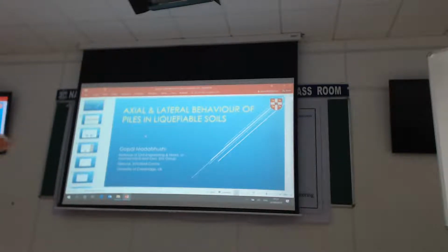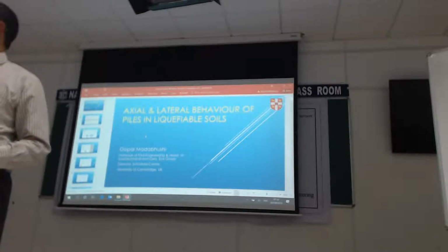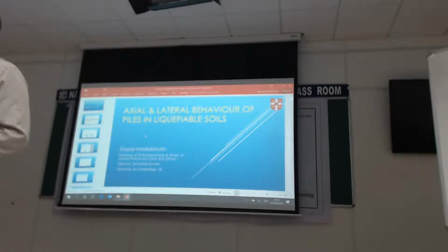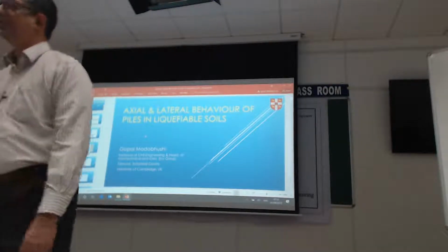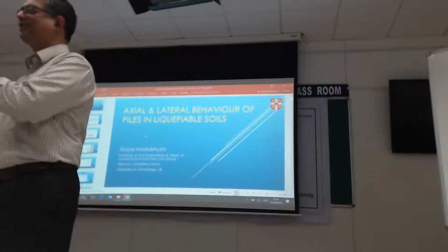If we want to run this whole thing as a 3D FLAC analysis, for example, you should be able to pick this up. In fact, a lot of the Iranian papers I was talking about earlier had a go at trying to simulate buckling with FLAC 3D. Of course, you can. Nobody said you can't. Once you know what's going on, it's not a problem, especially if somebody else has already coded into FLAC 3D Nor-Sand, PM4Sand, whatever the constitutive model is. Of course, you can do it. You will get the same behavior, I'm pretty sure.